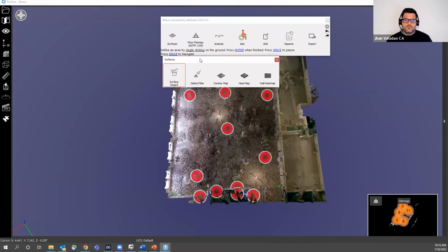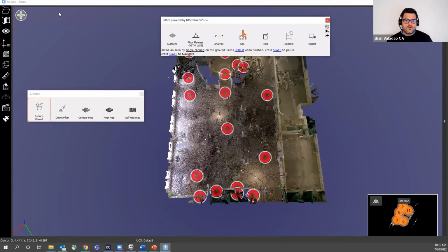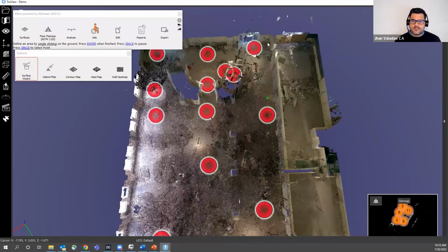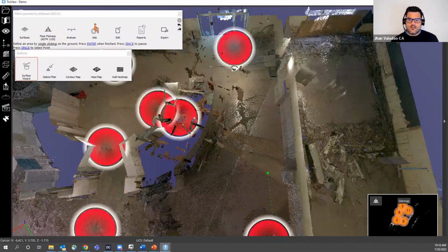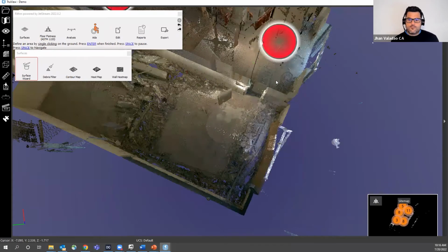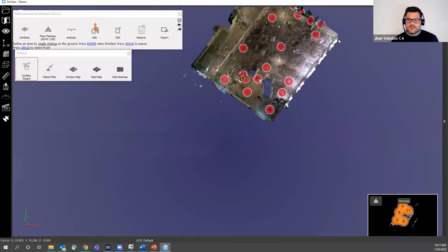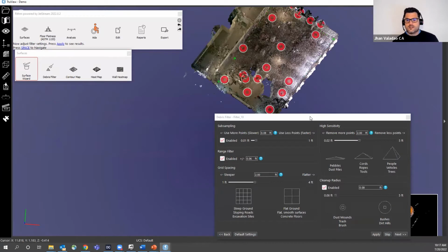Now, I've got all these panels right above me, and it could be a little difficult for me to see the wall. So what I can also do is press spacebar. That pauses the tool for me, and I can now navigate into an area that's a little bit better visible for the floor. Press spacebar again, start the tool, and then I can press spacebar out, spacebar, just so that I can see how to finish this. I think that's going to be okay. So I'm going to press spacebar, so I'm back in the tool, enter, and that closes it up.